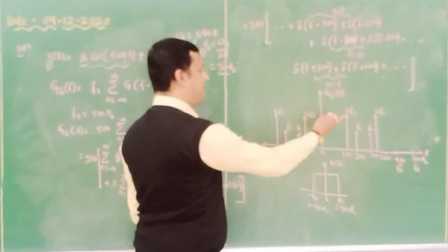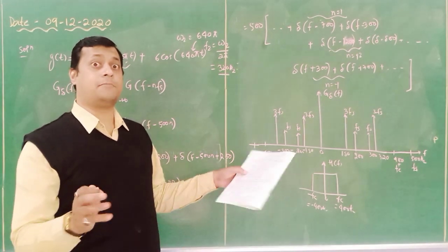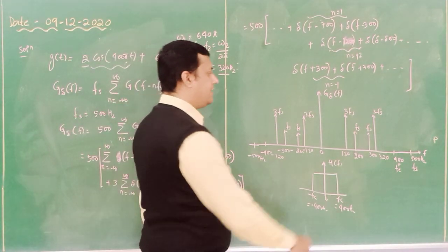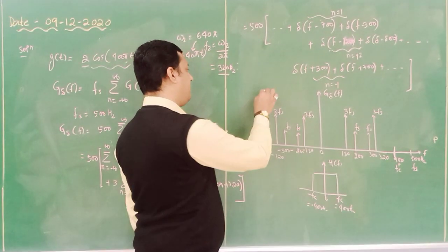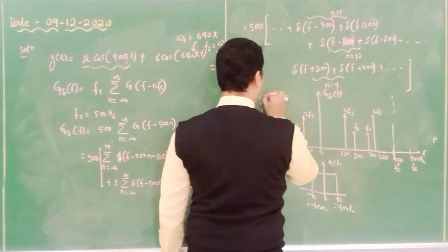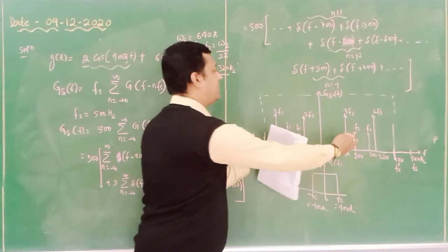So when this sample signal enters this low pass filter, what are the spectral components we can identify? Now here you can see that 400 is here as well as here. So if my low pass filter response is up to this much, that means I am not losing my information. All these spectrums are available.